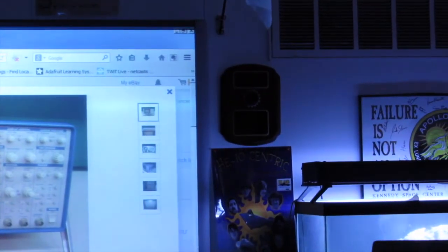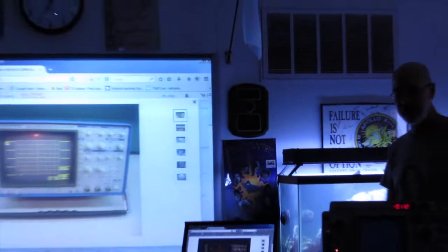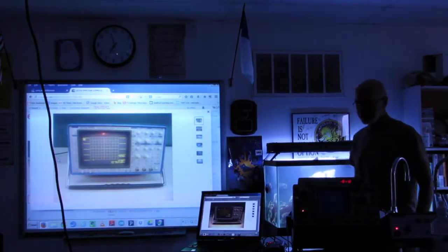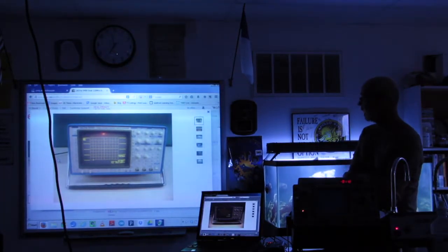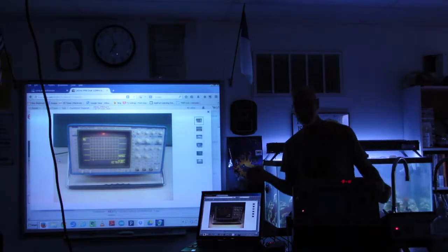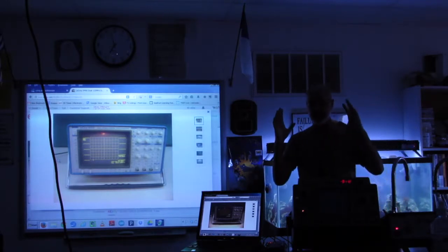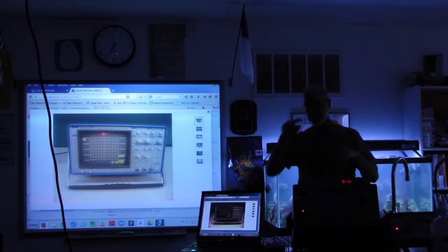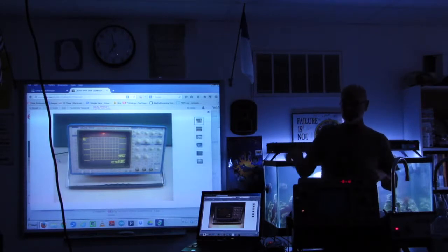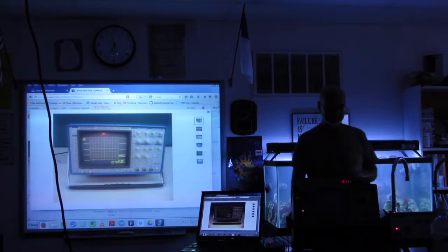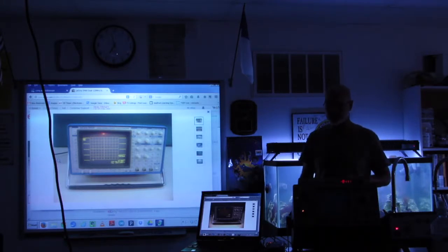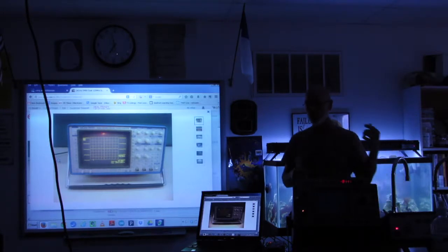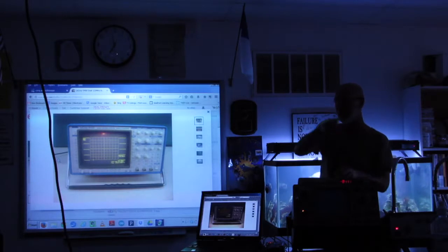Because of that, there are some disadvantages to it, but there are definitely some advantages to it. The way a digital scope works is you've got a memory buffer, which is arranged in a circle. It's a very high speed RAM, okay? It's basically what's called a dual port RAM, which means you can write to any address and simultaneously read out of any other address, okay?